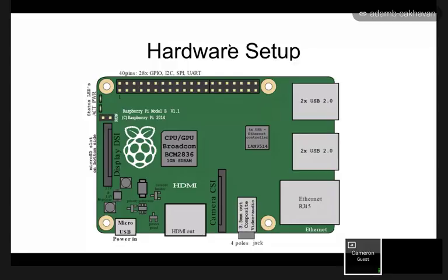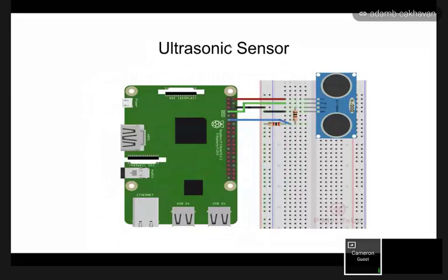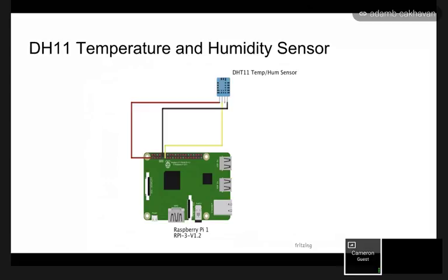You can actually Google Raspberry Pi pinout. But installing IoT devices is not as complicated as it looks. Pretty much the standard for any IoT device is that it has 3 or 4 pins: usually a power, a ground, and a data pin. In this case, for an ultrasonic sensor, it has a trigger and echo pin. All you need to do for any IoT device is put it on a breadboard, which is a little prototype board, and connect it accordingly. You don't even have to worry about this. You just go on the website for, let's say, the DHT11 temperature humidity sensor. All you have to do is Google the schematic online, such as DHT11 Raspberry Pi schematic, and it'll show you exactly what pins to connect it to, and which pins are the power.